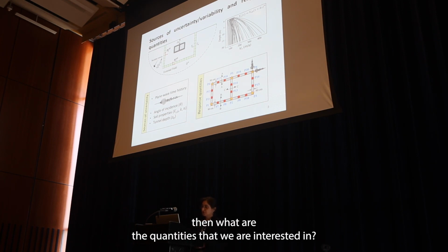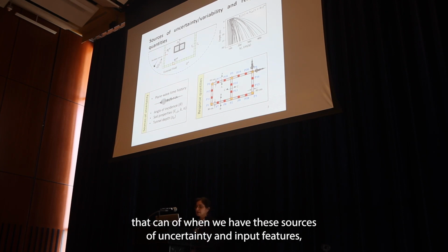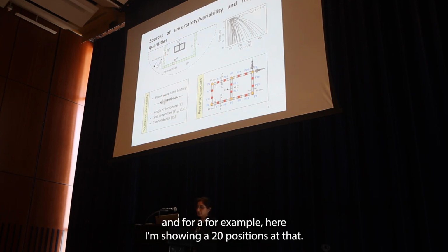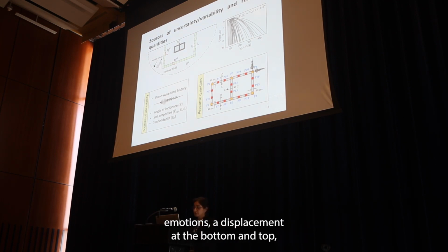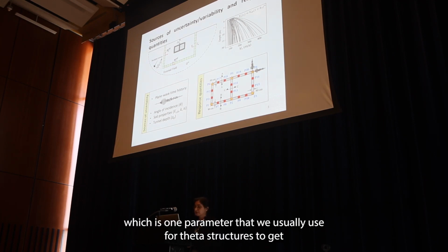Then what are the quantities that we are interested in? We wanted to see if we can have a surrogate model that, given these sources of uncertainty as input features, can predict the response in terms of, let's say, displacement time history at different locations on the buried structure. For example, here I'm showing 20 positions where we wanted to predict the response in both horizontal and vertical directions. With that, one can imagine we have displacements at the bottom and top, and we can compute the racking if someone is interested, which is one parameter we usually use for buried structures to get their performance.